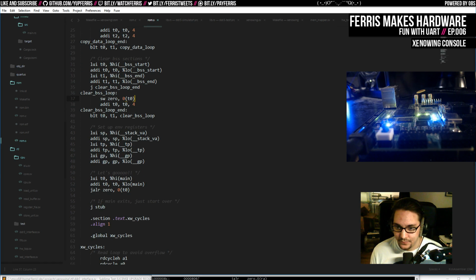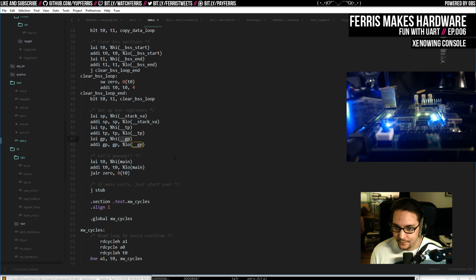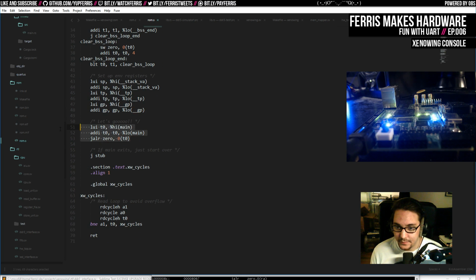So there's that. Then we set up the registers, and these all just come from the linker script. And then we jump into main. In fact, we call it, and then we'll jump to the stub in case main returns. It shouldn't do that, but in case it does, that solves that problem.